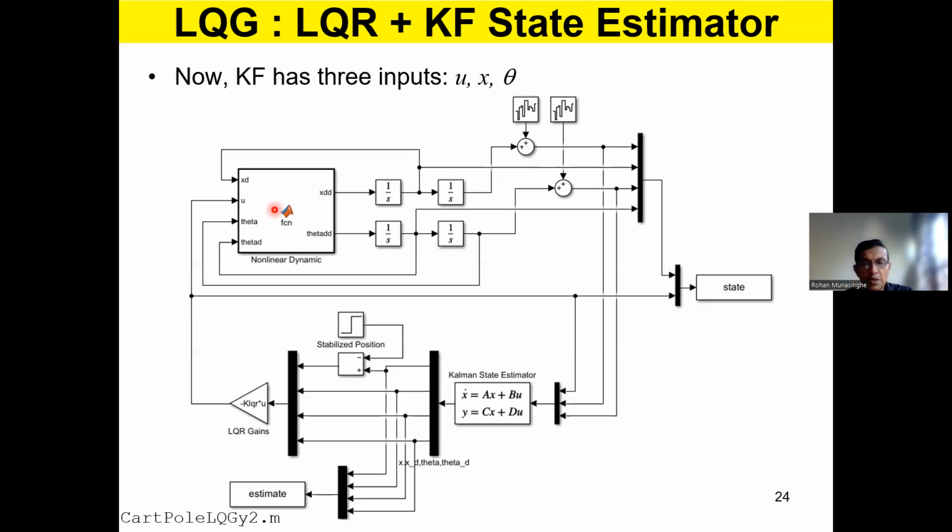So the estimation process inside the Kalman filter uses the system dynamics. It uses the system dynamics and estimates or predicts the state variables. Now, if the actual system is a little off from the operating point, the linearized state, this estimator is not able to accurately predict the state variables.